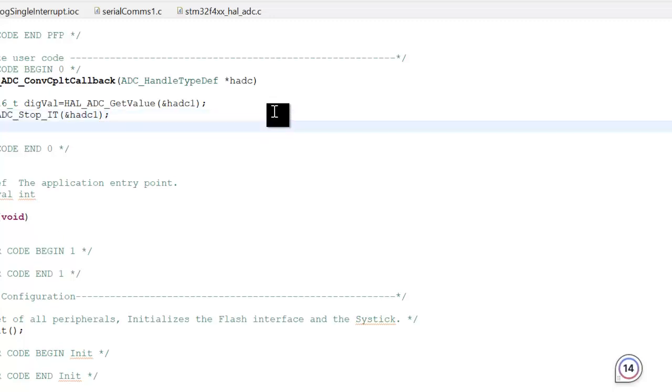Then I want to display the value. So we can write something like sprintf into the tx buffer. Double quote, \n\r. The first value that we have is the digital value equal to %u, unsigned. Then maybe we can type a tab,